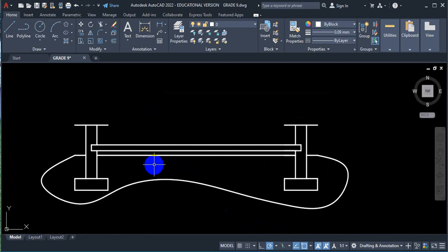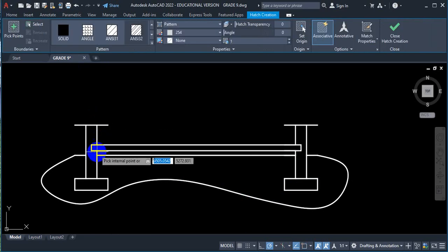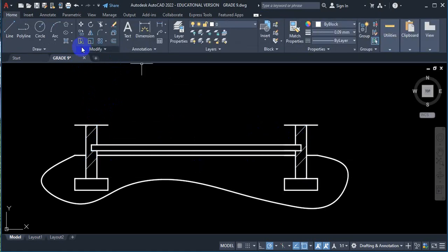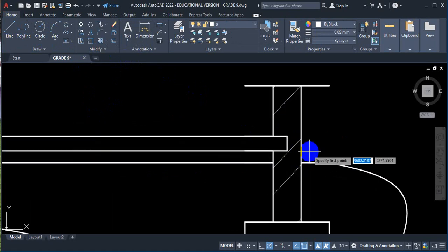So with regards to sectional elevation, as we said, almost everything is done here. So all we need to do now is do hatching. Firstly, we will hatch the walls, which is common brick. Common brick, meaning there's 2 lines. On the walls itself, there's one more thing that is missing here, your DPC line. You draw your DPC line, that's one.